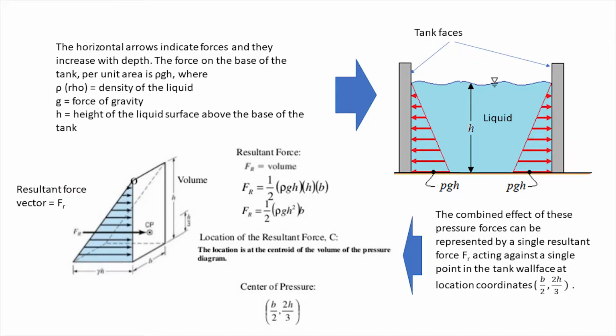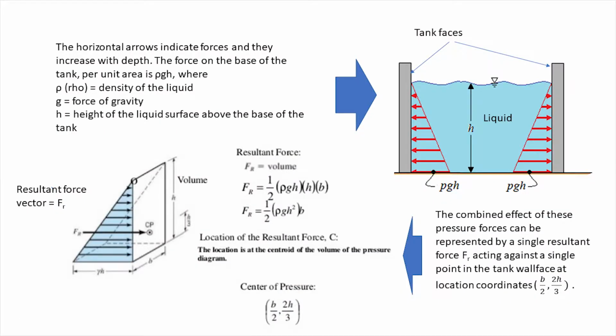Principle 1. A rectilinear tank filled with water exerts pressure on all of its vertical faces. In fact, the force operates at a point in the middle of a face and 2/3 of the way down from the free surface of the water. You can, of course, calculate this hydrostatic pressure, as it's called, for any shape of tank. It doesn't have to be rectilinear.